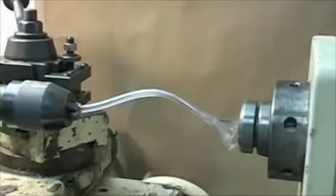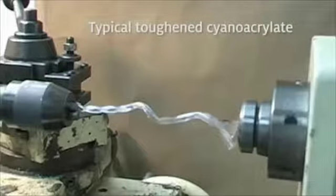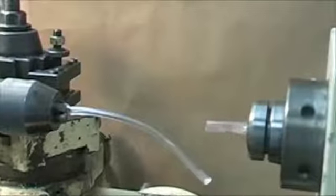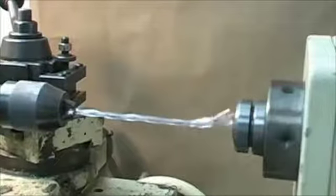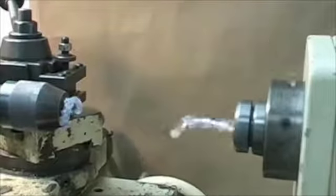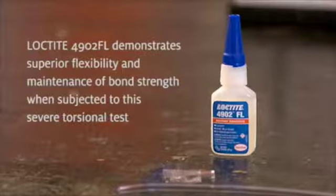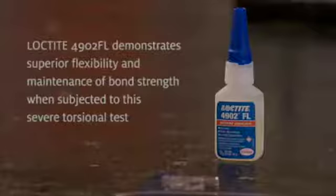Here we demonstrate through an extreme torsional test the typical strength of a traditional tough cyanoacrylate. You see that due to the adhesive's rigidity in the bond line, that it fails at the tube connector interface with approximately 4 rotations. With Loctite 4902FL, after more than 30 rotations, the tube or substrate breaks, yet the adhesive bond line remains intact. Loctite 4902FL demonstrates superior flexibility and maintenance of bond strength when subject to severe torsional tests.